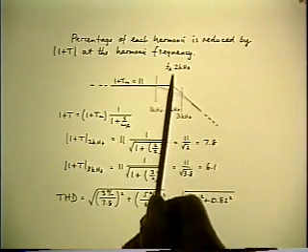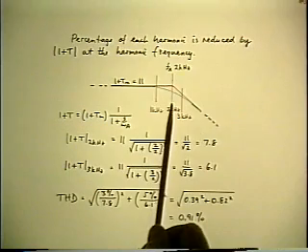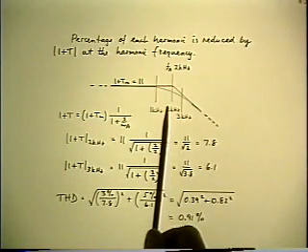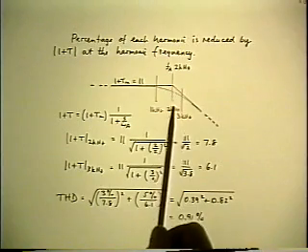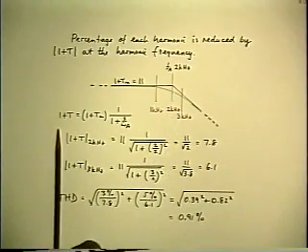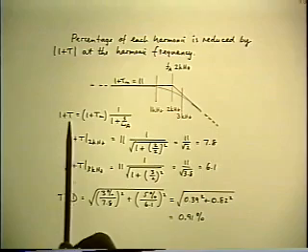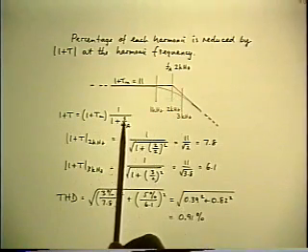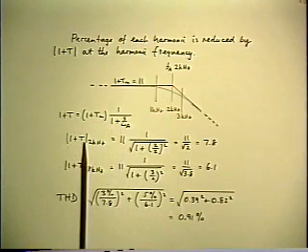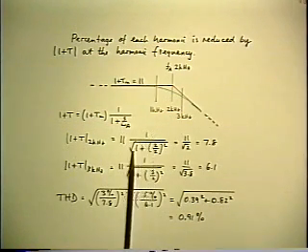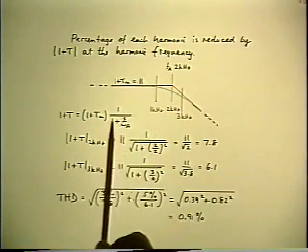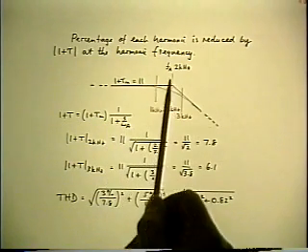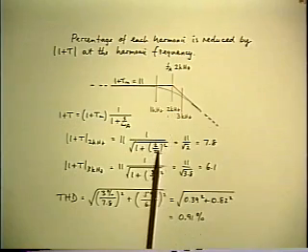So when I say you evaluate the F, what I mean is you find the magnitude of F at the second harmonic frequency of 2 kilohertz. So here's F, or 1 plus T, which is the flat value with the pole at 2 kilohertz. So the magnitude of that is 1 over the square root of the sum of the squares of the real and imaginary part evaluated at the second harmonic of 2 kilohertz.